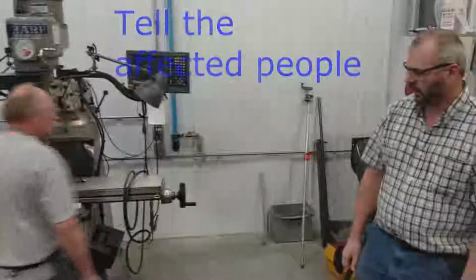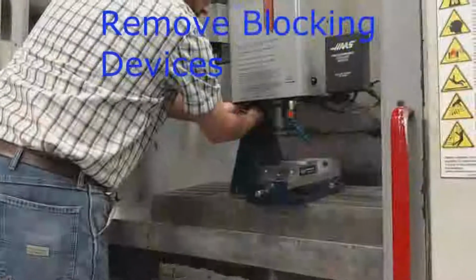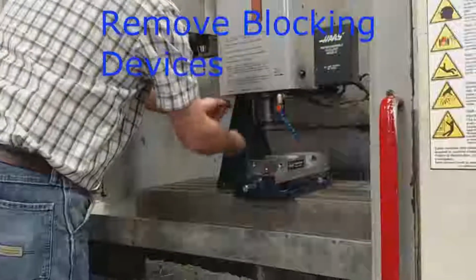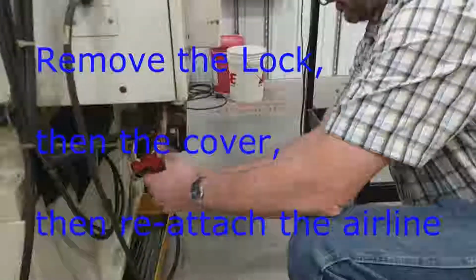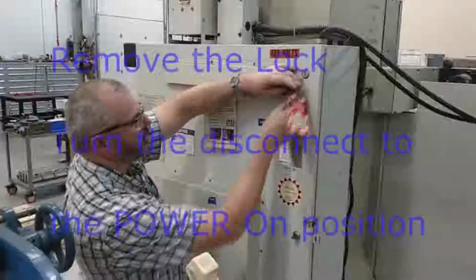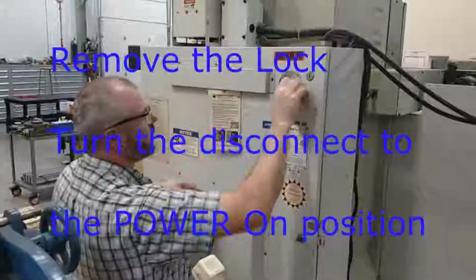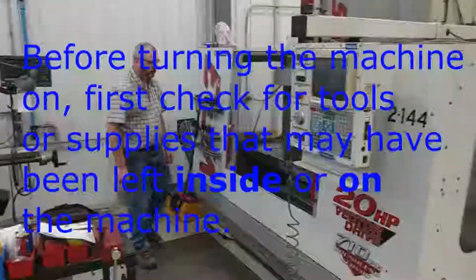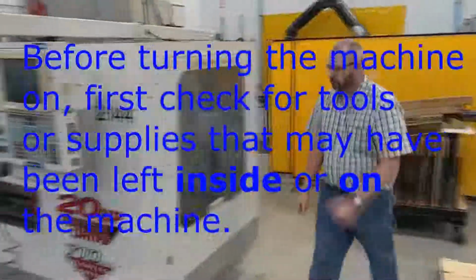Pete, I'm gonna put the Haas back into service. Okay, Tony. All right. Remove any blocking devices that were installed. Remove the lock, then the cover, then reattach the airline. Remove the lock and turn the disconnect to the power on position. Before turning the machine on, first check for tools or supplies that may have been left inside or on top of the machine.